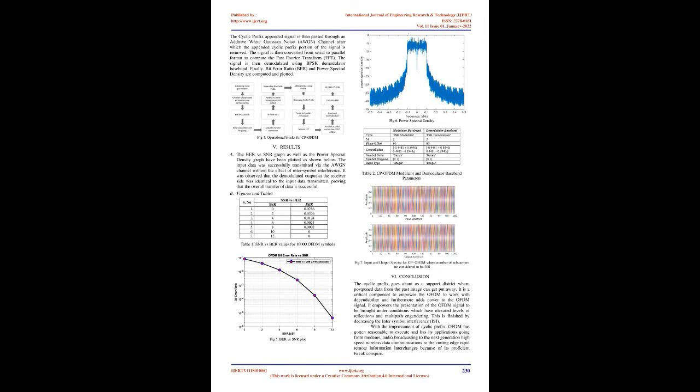The symbol is extended so it is 1.25 times as long. To do this, the back of the symbol is copied and glued to the front. The symbol source is continuous, so in reality only the starting phase is being adjusted and the symbol period is being made longer. This procedure is called adding a cyclic prefix.